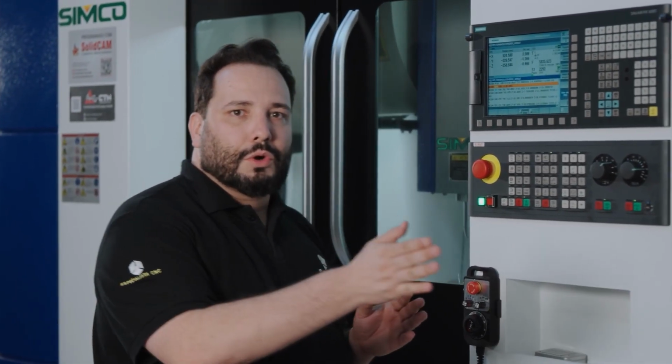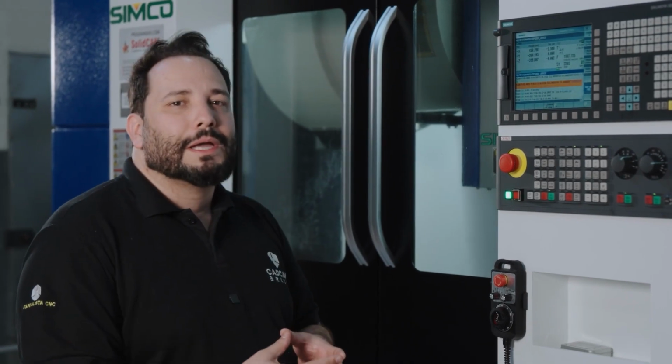Besides all that, there's something else here that I find even more interesting, which is this. In the traditional process, when I started going through a curve, removing more material, I would get vibration. Now I don't have that vibration anymore. The speed is so well controlled that I don't get vibration on any of the part's profiles, whether I'm removing a little material, a medium amount, or a lot of material. That really impressed me.